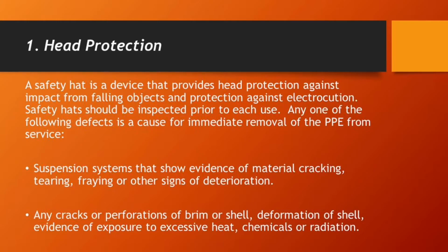Suspension systems that show evidence of cracking, tearing, fraying, or other signs of deterioration. Any cracks or perforations of the rim or shell, deformations of the shell, or evidence of exposure to excessive heat, chemicals, or radiation.